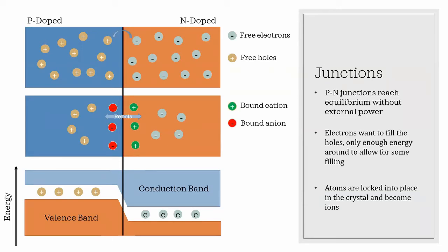And a very similar thing happens on the positive side. If we think of the holes as particles, they're trying to diffuse across and fill the atoms on the other side, but we have a positive region that kind of stops that from happening. Eventually, we're going to reach an equilibrium, and the region at the junction effectively stops the flow of electrons from one side to the next. This region is called the depletion region since the electrons in this area have all left. They've all moved on. And this equilibrium region creates a difference in the energies on either side of the junction.